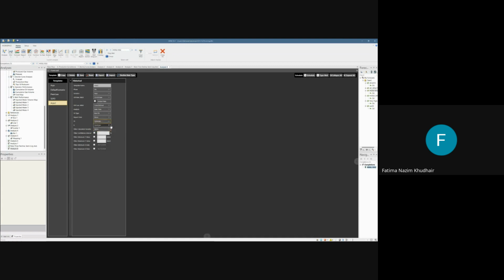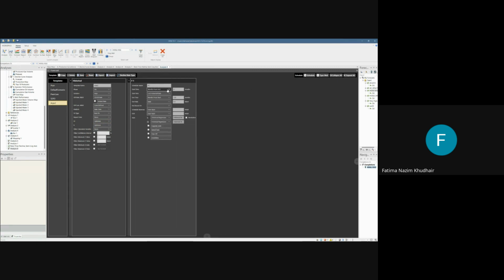Also, keep the general settings for optimizing the p-value, DI, and so on. And then we're going to add schedule. Your start time, I'm gonna keep it from month from end. And also the start rate. Okay, keep it historical rate. Here's the end time. After what time the forecast will be ended. Here's 120 months, 10 years. And your end rate, keep it rate. At this rate of prediction, your forecast will be ended.